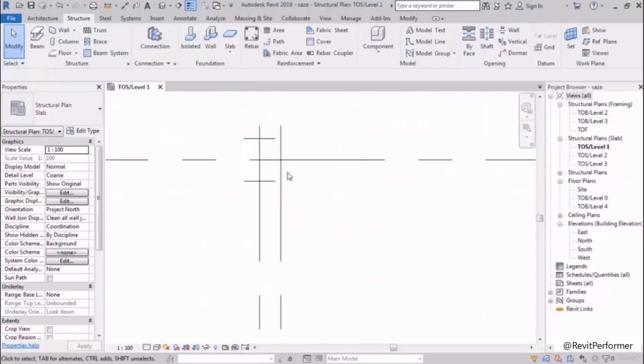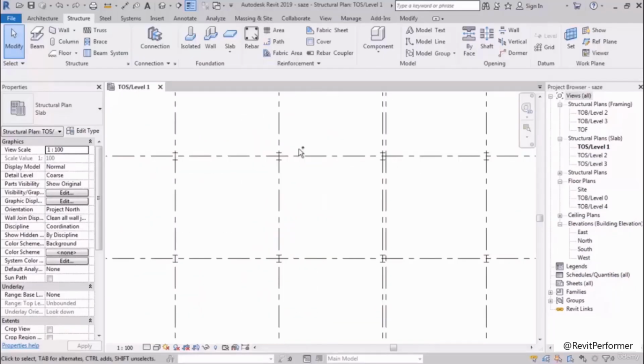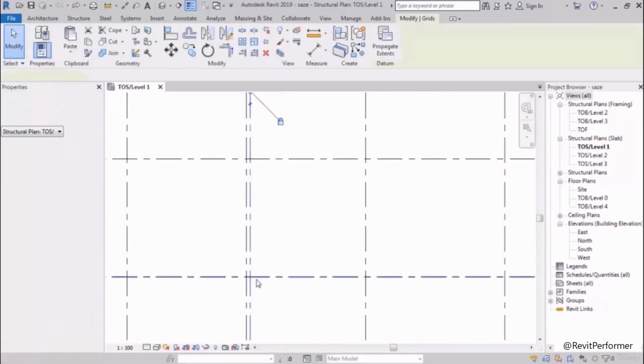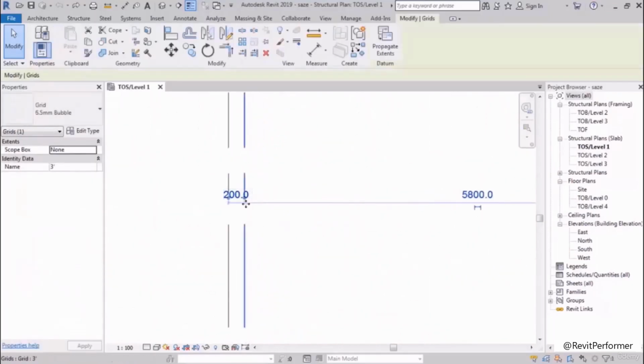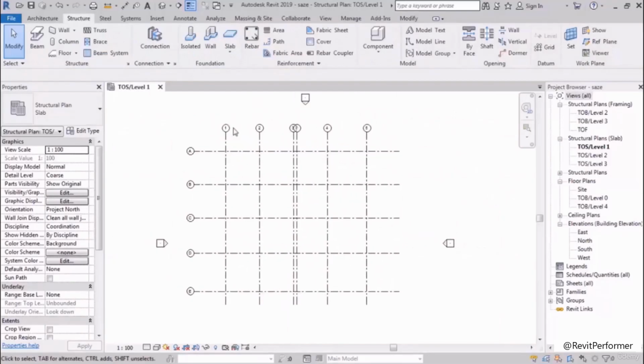Right. The second part is about the gaps, some gaps. Why is it not placed here? Well, when the columns go into each other, it is not placed. So the distance between the two grids must be noted so that the two columns don't go into each other. So we can just undo, fix it, or for example, increase the distance, based on the size of the column, for example, 60 centimeters.